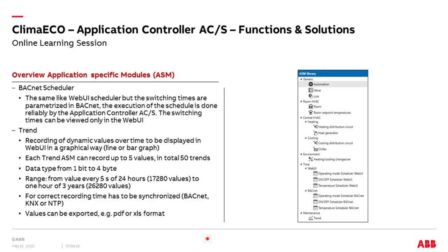Just in case of any malfunction of the BACnet system, the time function is still running reliably on the KNX side. That's the target here. So you split this here if you want. There's a request very often for having such a function.